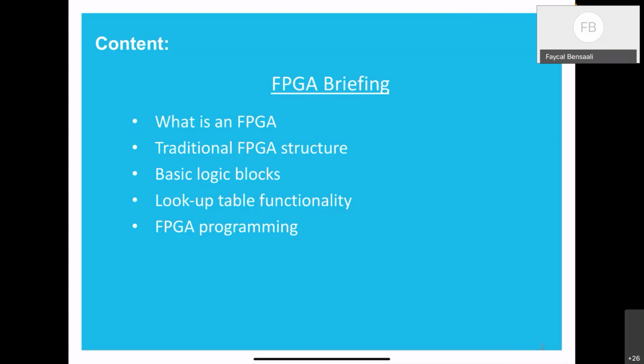If you want to describe an AND gate, you should write the description. There should be no syntax errors in your description. And then when you test it, it should work as an AND gate, not as a different gate. So we can do simulation as well to make sure that this is correct.